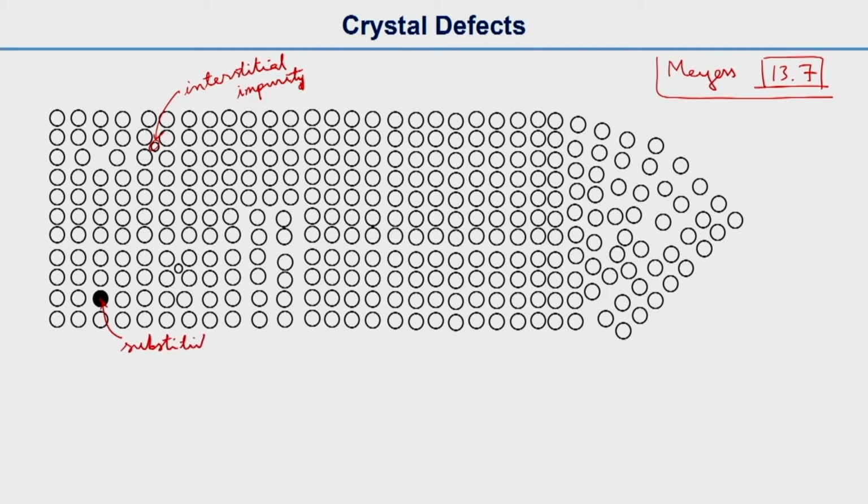Substitutional means that the atom is different. Let's say all the other atoms are aluminum, and one atom is a copper atom, so that's why it is called a substitutional impurity. There can be a high number of impurities, but we are showing only one for each. And then this is an extra half plane, that is the dislocation. Actually, the dislocation is the line perpendicular to the plane of this slide. This is actually an edge dislocation.